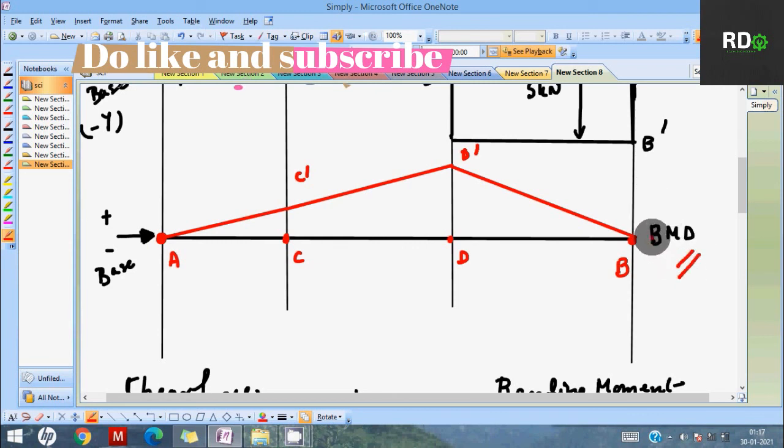So this is how you draw the bending moment diagram, BMD, for a simply supported beam. It's very easy. First find the reactions RA and RB, which I have found out. Then find the shear forces at each point and draw the shear force diagram, then find the bending moment at each point and draw the bending moment diagram.